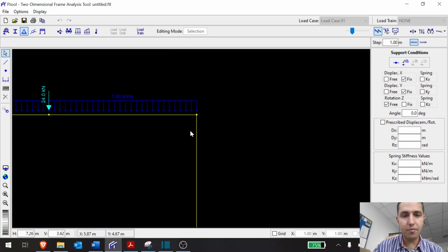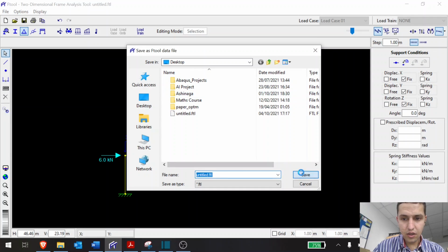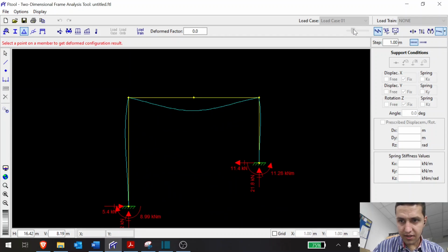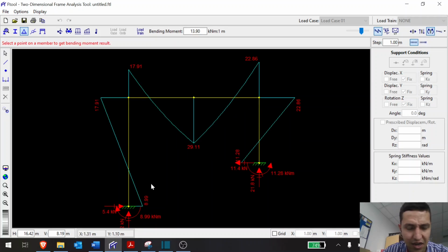So let's try another model. Let's say, for example, we do the same thing, but now with fixed supports everywhere. Okay. So if we see now the deflection, we're going to get something a little bit more complicated. Let's have a look. Let's make it bigger. But now we can see there is tension on the right, then tension on the left, and here tension on the top, then bottom, then top, and here tension on the right, and then it has to go tension on the left to close down. If you go to the moments, that's exactly what you see. Right and left, then up, up, and then right, and then left.